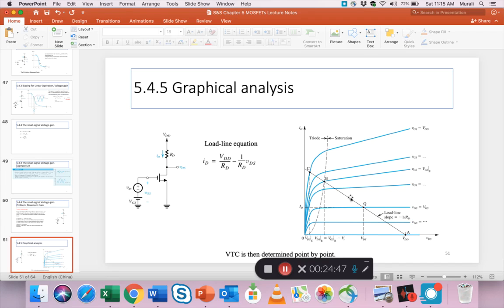You can do it with this relationship of VDS to ID with these graphs, with these straight line sections, as given by the manufacturer and the load line. So this is one approach. You can put your input signals here and take the output out of here or out of here. That's one approach. The other approach is to use the VTC. There's another third approach I'll show you in a little bit.